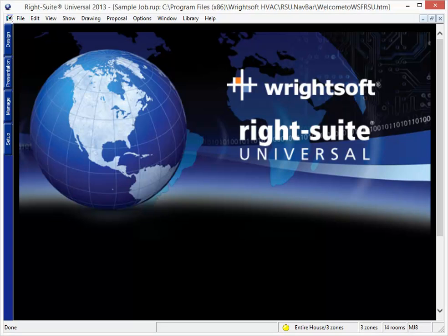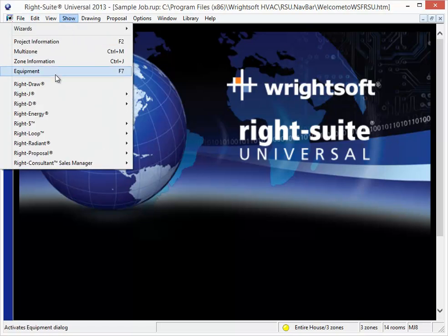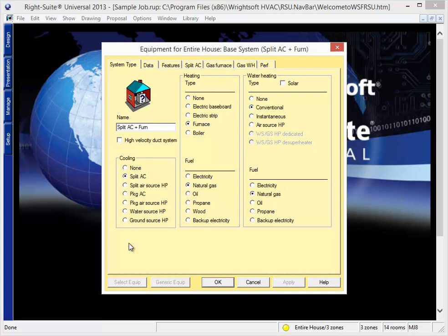In this video, we're going to look at Wrightsoft's automatic Manual S equipment selection tool. Once you've done a load calculation and go to our equipment selection screen, you may have the opportunity to use your manufacturer's extended performance data in conjunction with Manual S methods and recommended ranges to find the appropriate piece of equipment from your manufacturer. Now, this will largely depend on whether or not your manufacturer has provided its extended performance data to Wrightsoft.